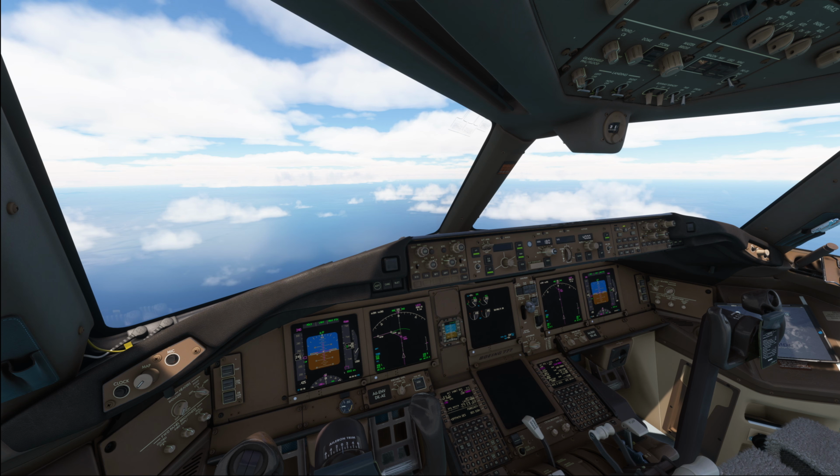The speed window can be opened and command speed can be set while VNAV remains in VNAV path descent mode, so it does not revert to VNAV speed, and then VNAV commands the set speed. The MCP altitude can be set above the airplane altitude for the missed approach, and when the MCP altitude setting is at least 300 feet above the current airplane altitude, VNAV continues to command a descent.